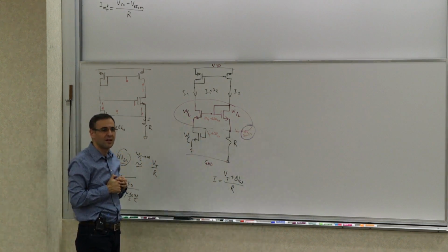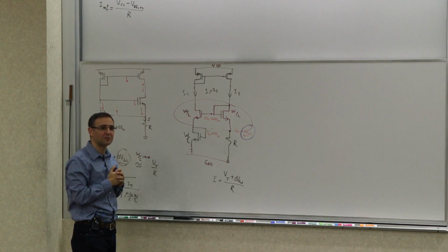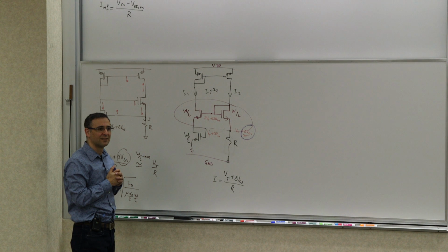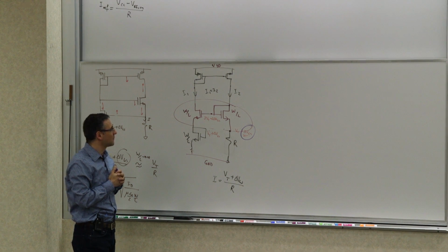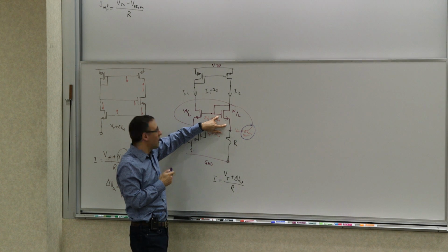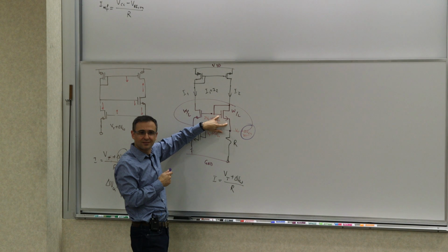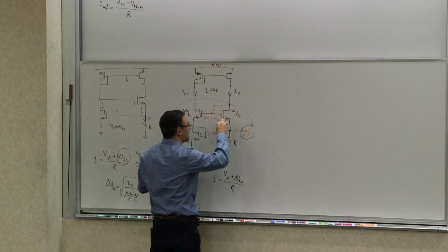Do you agree? Can you think of a W over L trick that would allow you to get rid of it? You want to drop what here? Yeah, cut the middle to W over 4. Because you are trying to drop a Vt plus 2 delta VGS here, and to get Vt plus 2 delta VGS across here, you can cut this by a factor of 4.